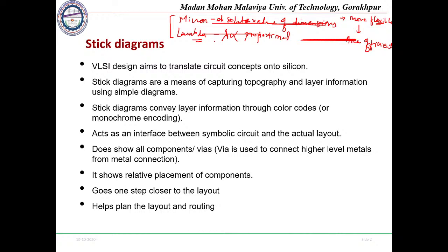Along with that, in case of the micron rule of layout designing, the user has the power to define all the layers separately, based on the dimensioning of the different layers. But in case of the lambda rule, there is no role of the user.